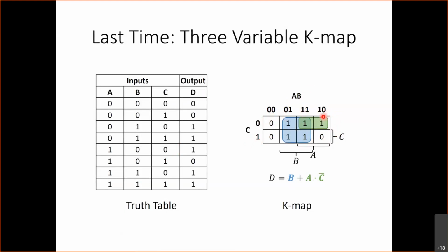And this was essential for us for the Karnaugh map technique to work. And so here, that's why we had 0, 0, 0, 1, and then 1, 1, 1, 0, as opposed to 1, 0, and 1, 1. Because if you put 1, 0 over here, then we would have two bits changing at a time between this column and this column. And if we did that, then the Karnaugh map technique would not work.